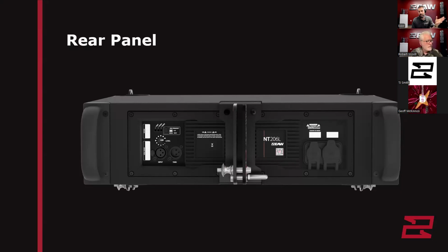And even with that in mind, you could adjust the bottom of the array to 110 degrees to improve and even out the coverage in the near field. So even though we've removed some of the DSP capabilities, we're still giving you plenty of options to optimize your array when you start combining that high frequency button with the horn flare and the fact that it's adjustable.